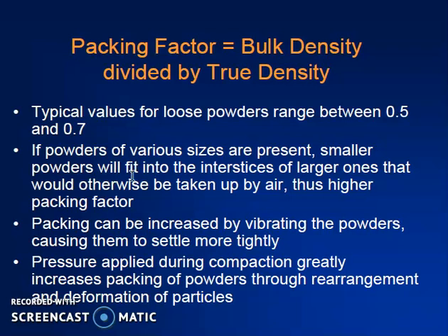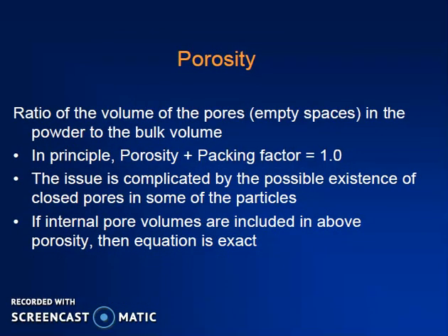Packing can be increased by vibration given to the powder, causing it to settle more tightly, and pressure applied during compaction greatly increases the packing of powder through rearranging and deformation of particles. So this is important: how to enhance the packing factor of any powder.